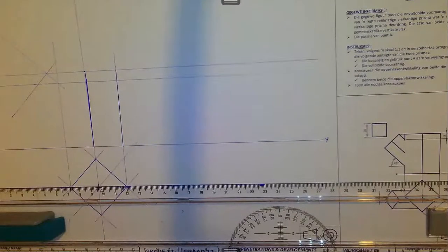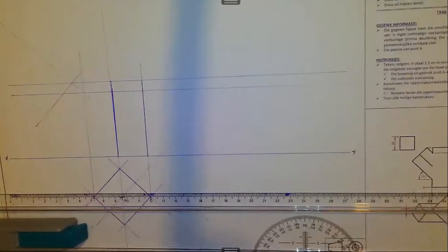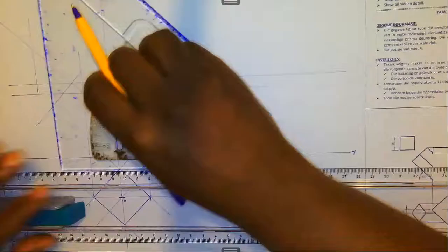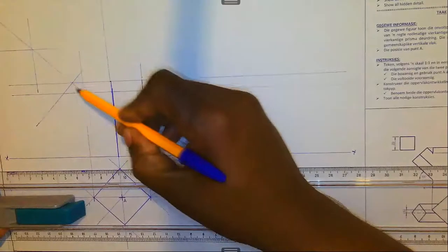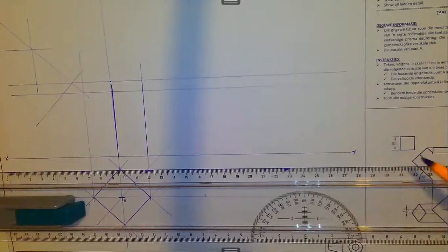Right. Now, once you have done this, the next thing that you want to do is to construct the auxiliary view such that you'll be able to project backwards that side, okay? Right, so you can just start from somewhere. You would find, I can just start here. Right, that is my upper part. Then this corner is in line with that corner. Right, and what is the size of the auxiliary view? It is 20 millimeters. Right, then you measure 20.